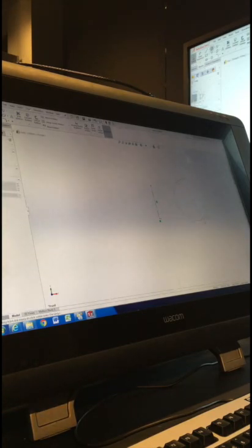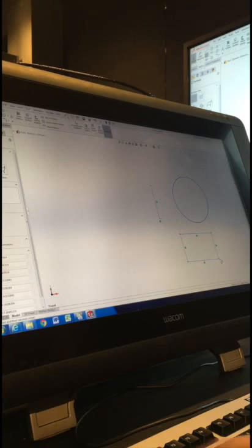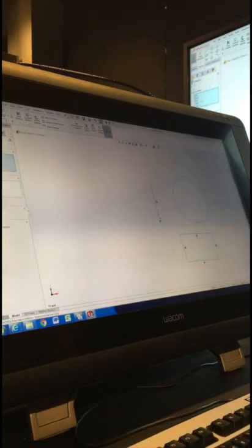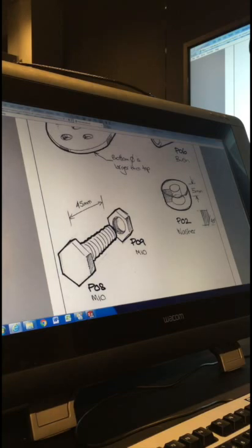They're just there as a guide. Construction lines can be any sort of shape. Anything can be a construction line just by ticking that box, and you can always uncheck it if you want to use it again for something else. So what we're going to sketch is this shape here with the 45-degree angle. We've got 2 dimensions, the angle and the 5mm height.